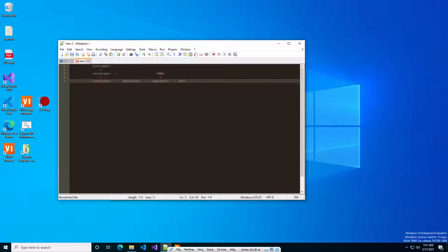You may have a different test platform with a different DMM in it, and you don't want to rewrite that code. So the idea with the hardware abstraction layer is that you write your tests such that when you want a DMM measurement, you call what we call the base class, the DMM class, and say, I want to take a voltage measurement. And then in the DMM class, depending on which child class you've instantiated, it will either call the Keithley library's DMM get voltage function, the Agilent's, or the NI's, depending on which one's hooked up to the system.